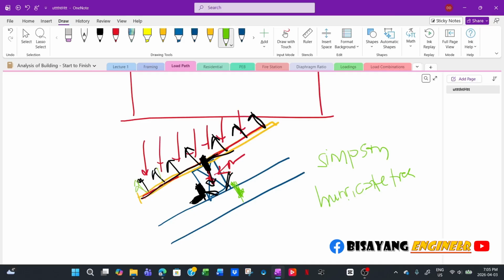So if you have wind pressure, you have uplift in this, even the sheeting or this roof cladding, it has to withstand all the loads. So usually manufacturers have a load table for these types of, say, if you use a 16 or 24 gauge metal roof panel, then it can withstand, say, the usual 40 PSF snow load or whatever. So you have to have a load table to determine what gauge to use for the roof.